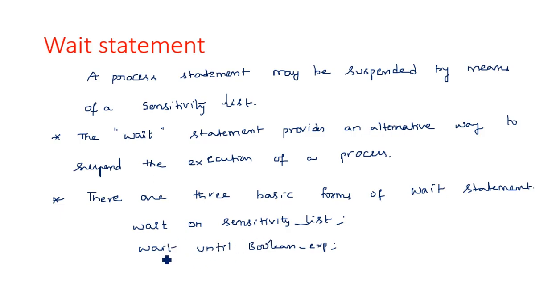So wait on sensitivity list, wait until Boolean expression, and wait for some time expression like 5 seconds, 10 seconds. Directly we will mention the amount of time for the waiting period.